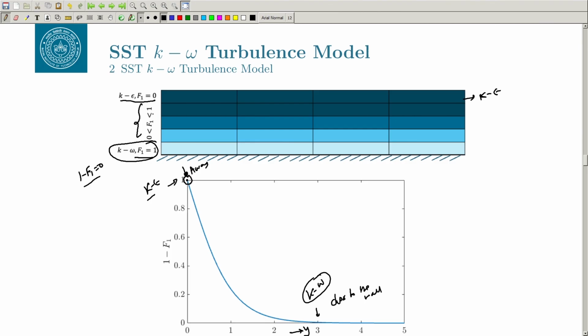to 0. It is not like at one grid point you have the k omega, and at another point the k epsilon, right. So, this is k omega and this is k epsilon. It will be a problem, because you are making a drastic change, and a drastic change is not good in any CFD simulation, whether it is a drastic change in the grid or in the flow parameters. The solver always has difficulty if you have a very drastic change.